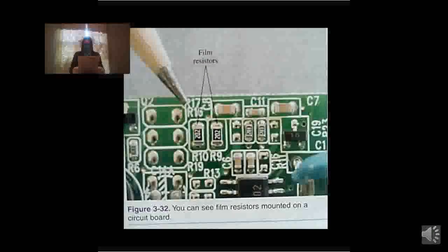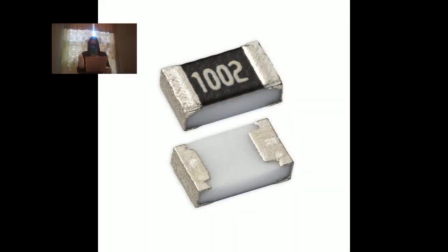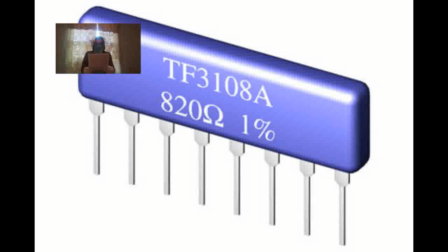The substrate is made from glass, ceramic, or silicon, and it is used as an insulator base for the resistor. A layer of resistor material is deposited on the substrate in a zigzag pattern precisely engineered to produce the desired resistance value. The resistor materials are made from metals or carbon mixed in a precise proprietary formula. The result is a thin film, which is only a few micrometers thick, or thick film, which is 10 to 50 micrometers thick. A protective coating is used to cover the resistor material deposited on the substrate.